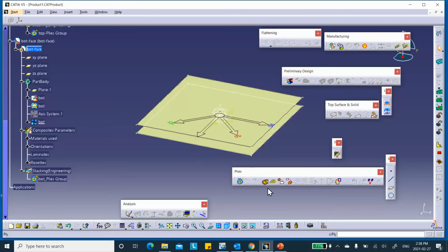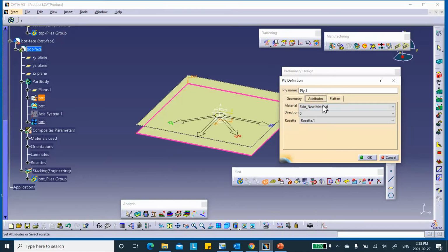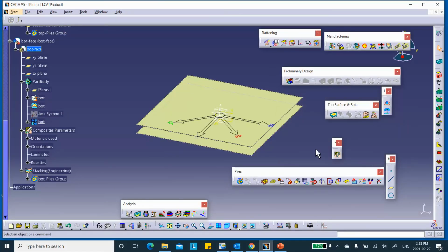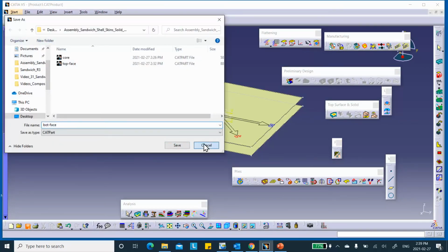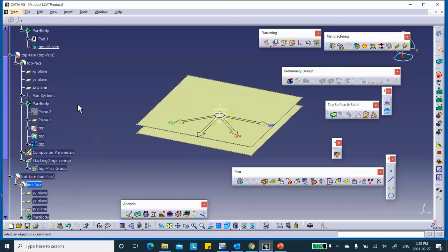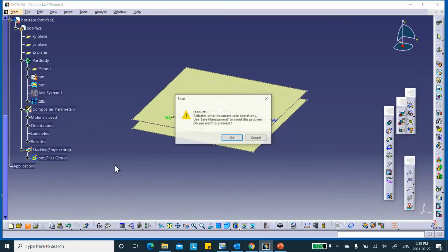Okay, and then I'm going to create the lamina, the single lamina that's there. So ply, single lamina or ply that's there. You select this. For the boundary, use the sketch, bottom sketch right there, and material and direction are correct. Okay, so save everything. To save everything, my suggestion is that you go to top level assembly to make your job easier, and then click on the save. It'll do everything for you.